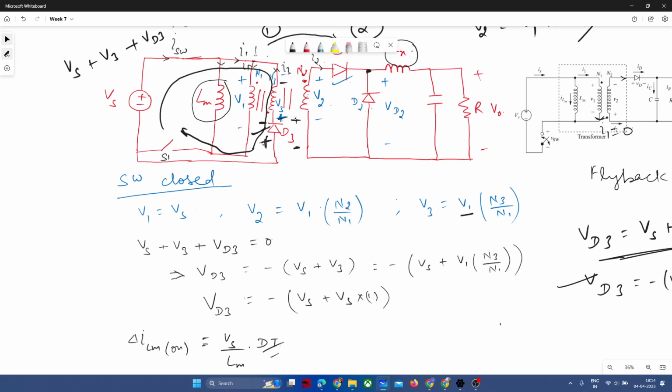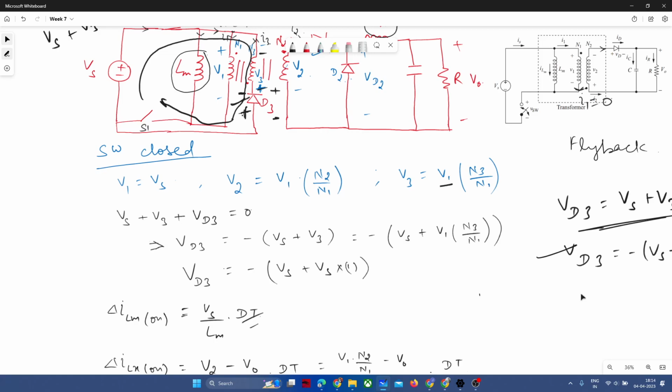So it was a very significant observation that the tertiary turns are there. It is connected to our supply voltage conductively as well as inductively. Voltage will be induced on the tertiary winding, and when the switch is off, it will be connected to the supply conductively as well. So the tertiary winding is quite a flexible path in this circuit. Generally we want a connection which can supply conductive as well as inductive, because many times magnetics are weak, when the air gap is large enough that it won't allow the flow of flux efficiently, and in those cases we shift to conductive, right?